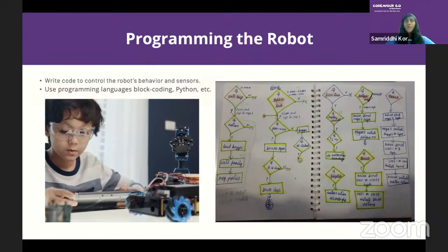And always one more important thing that I would give you guys is, okay, let me give you an example. You have a motion sensor in one part of the project and an ultrasonic sensor in the other part of your project. So imagine something is not working and you're not getting the right reading. What are you going to do? You don't know which sensor is not working, right? So I would advise you when you're testing your project, have individual codes just to test the component. So imagine the motion sensor is not working. So upload a code. If motion detected, then maybe serial monitor output that motion detected. Simple code. Just send the code, check if the sensor is working.